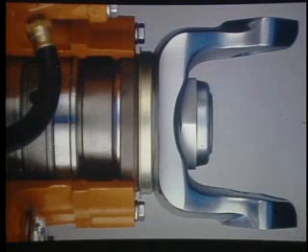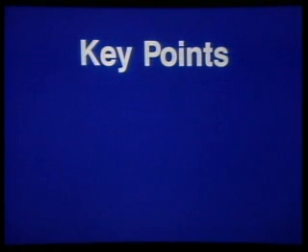This type of seal and yoke can now be ordered on most new production Fuller heavy-duty transmissions. The long-term operating cost savings that this type of seal technology offers makes it a must item when speccing a new truck. You can see that to properly repair a complaint of rear seal leakage, it is not as simple as knocking in a new seal with a ball-peen hammer and sending the truck back on the road.